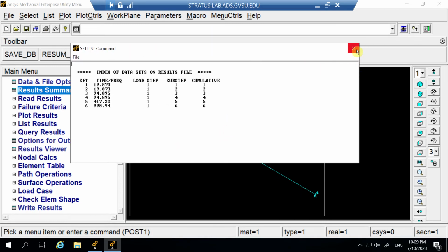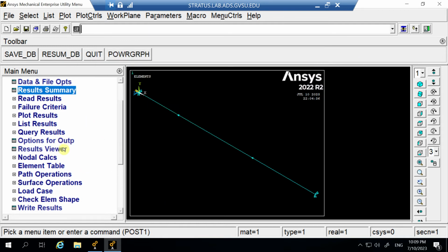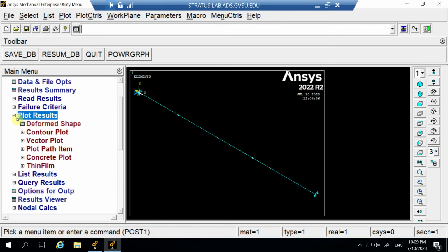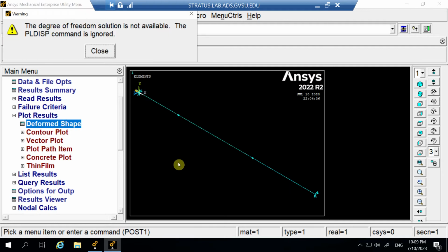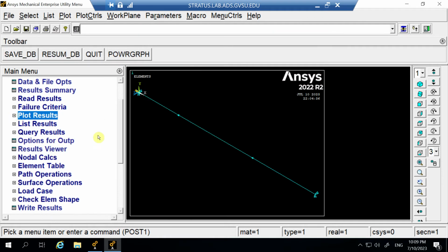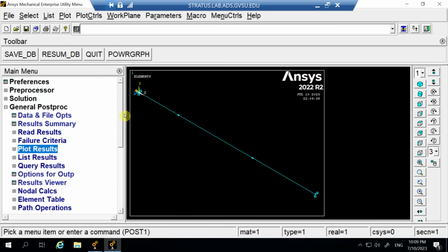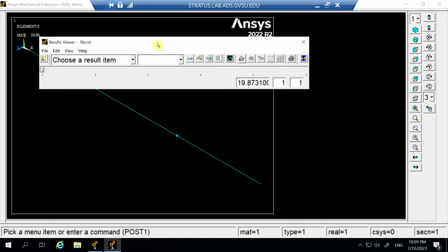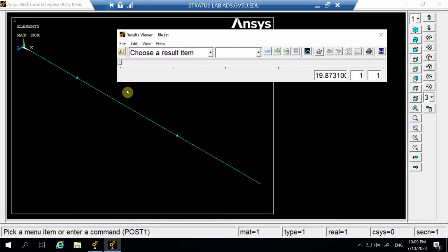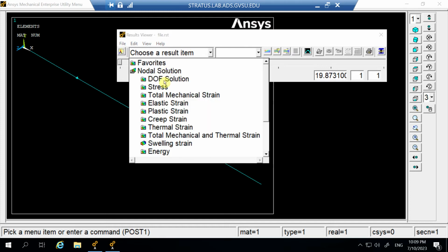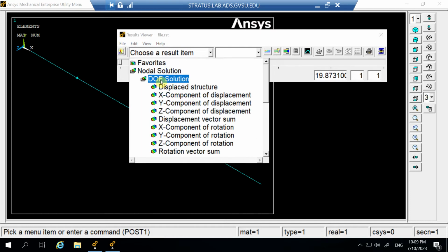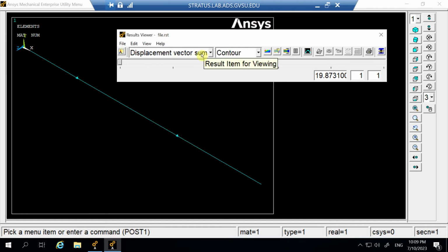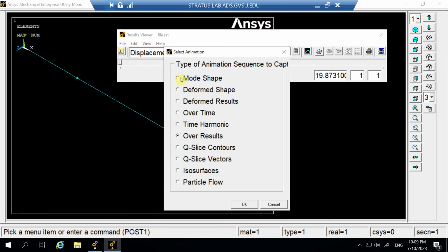So we can take a look at them, and you can look at the videos. Let's see how we can see videos. Our result here should go here. So for the first natural frequency, in the solution, you can come here and say, just show me the entire displacement. If I click this, I say, show me mode shape.